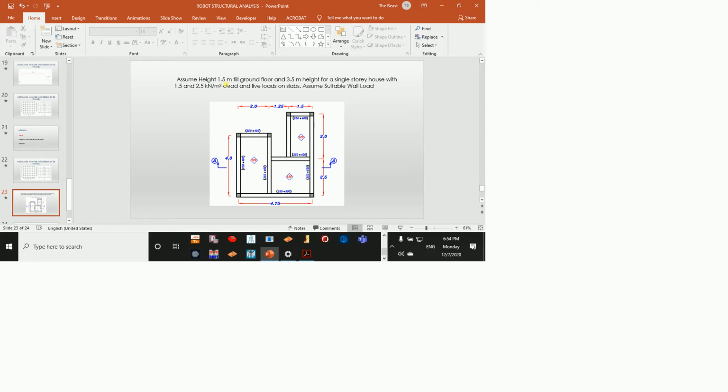Another thing to be taken into account is sunken slabs. We have a lot of sunken slabs here. A lot of people are not familiar with calculation of sunken loads, so that's another load to be taken into account. Depending on which material you are going to fill, some use sand, some use lightweight concrete, some use loose material.